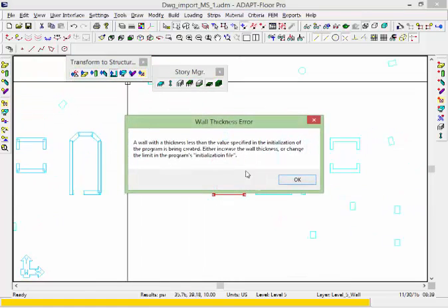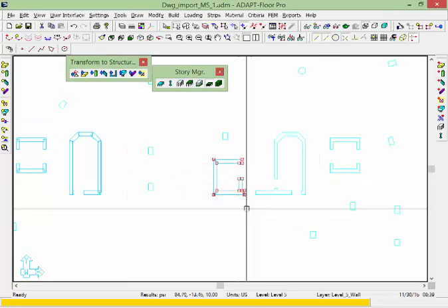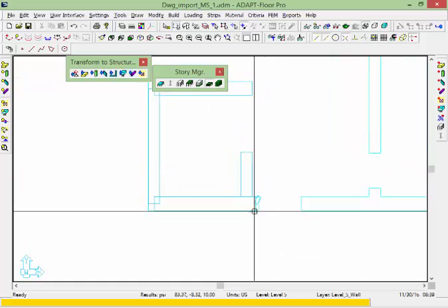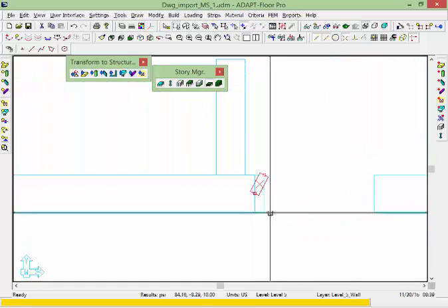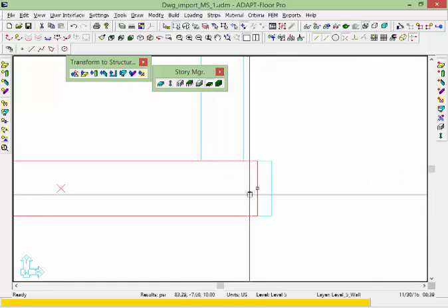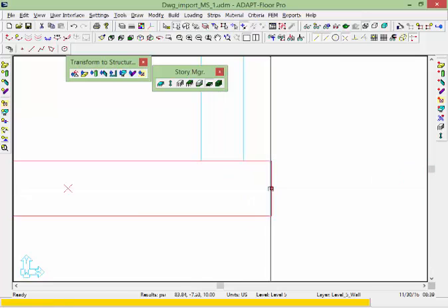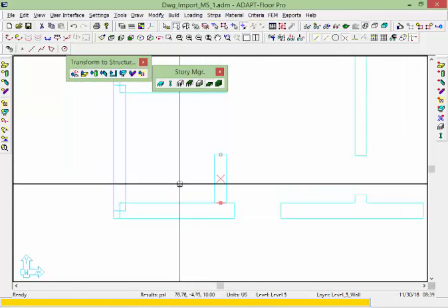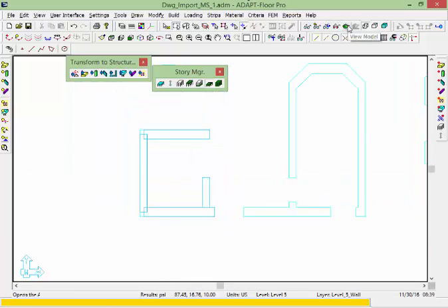And you can see this actually gives the error that there is a wall thickness less than what is required for the conversion. It looks like it's this wall right there. We'll just take this and shift that out to there. Okay, let's go and just review this wall, make sure it's being created properly so you can see the 3 wall groups.